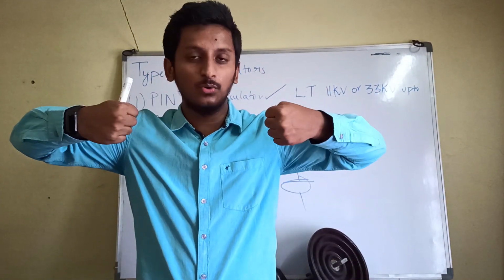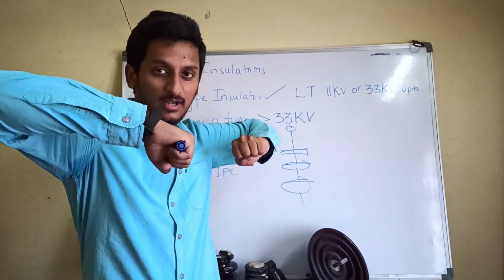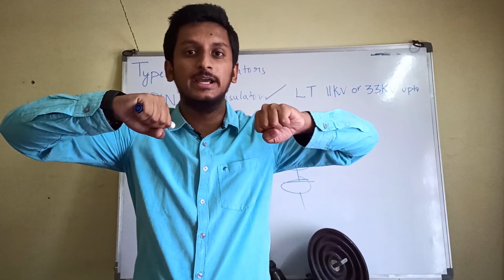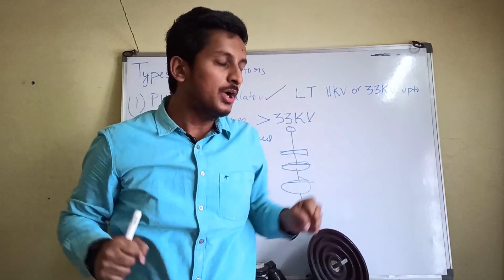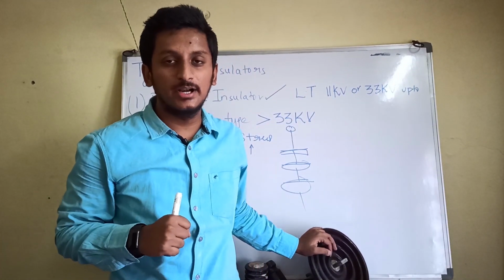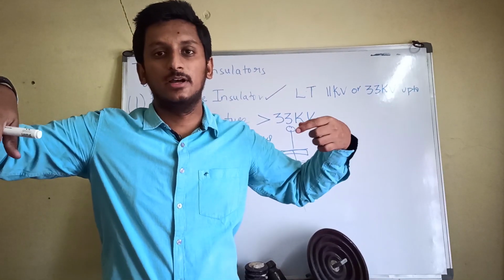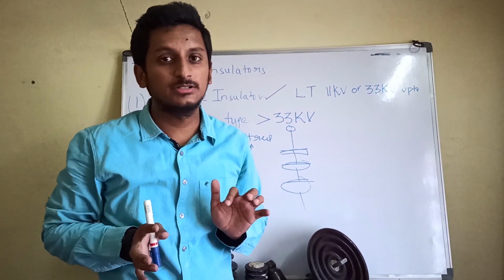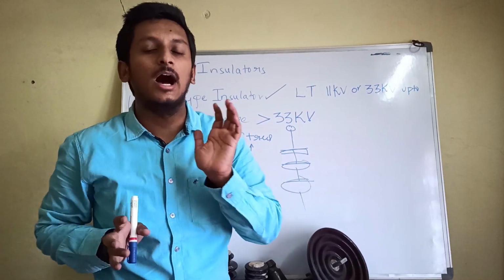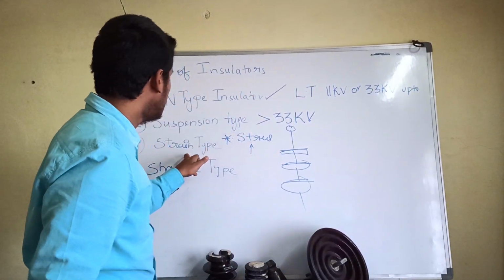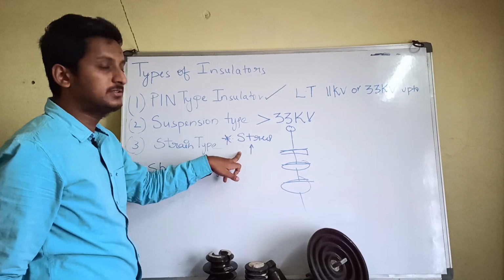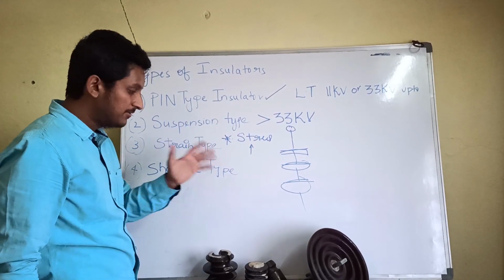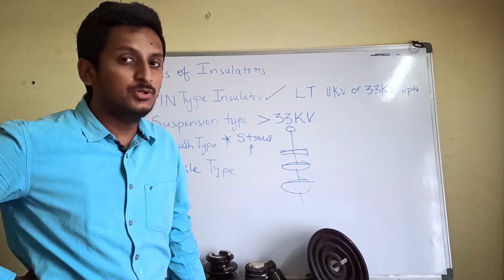Now when you take two edges, if there is a turning like this, the stress will be more at the sides of the insulators. So if you use this insulator disc at the turnings in the towers, that means in the transmission system, then this will be advantageous. Wherever the stress or the strain is more, you can use this kind of insulator.